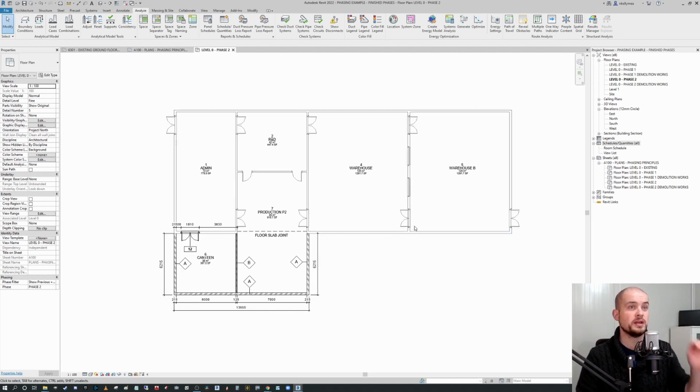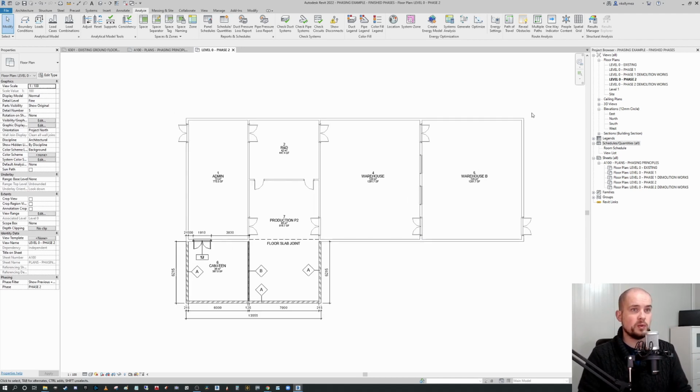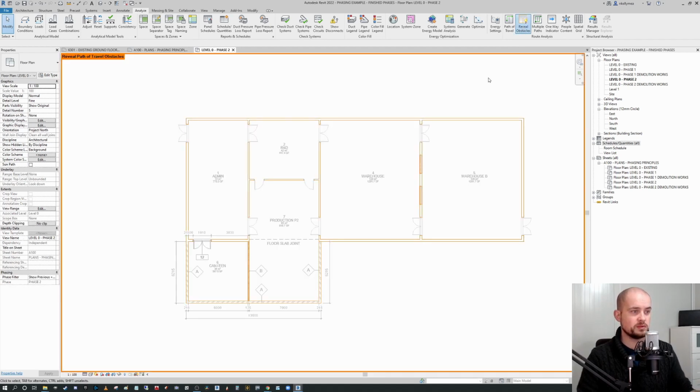But looking at the tools we have now, we can first of all reveal obstacles. When we select reveal obstacles, it'll automatically color everything that's designated an obstacle in orange. This is the same kind of presentation as you might have from hide reveal elements, but it highlights the obstacles as orange, and therefore it shows what the path of egress will not be able to go through.